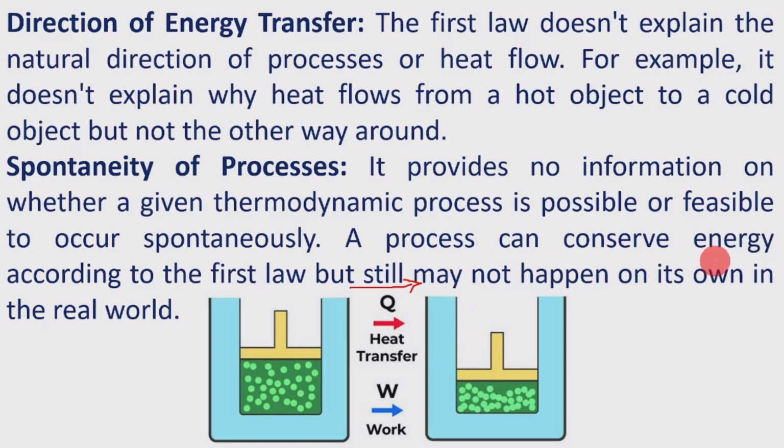A process can conserve energy according to the first law, but still may not happen on its own in the real world. In the real world, a driving force is required. From higher temperature to lower temperature, the temperature difference is the driving force, a potential for the transfer of heat. In the real world, that is not mentioned in the first law of thermodynamics.